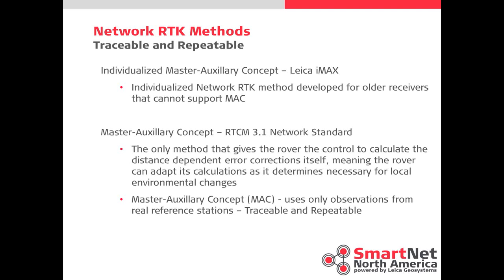So network methods with iMAX, it is an individualized network RTK method developed for older receivers that can't support MAC. And for Master Auxiliary Concept, RTCM 3.1, the network standard, it's the only method that gives the rover the control to calculate the distance-dependent error corrections itself, meaning the rover can adapt its calculations as it determines necessary for local environmental changes. With Master Auxiliary Concept, MAC is the only one from real reference stations that's both traceable